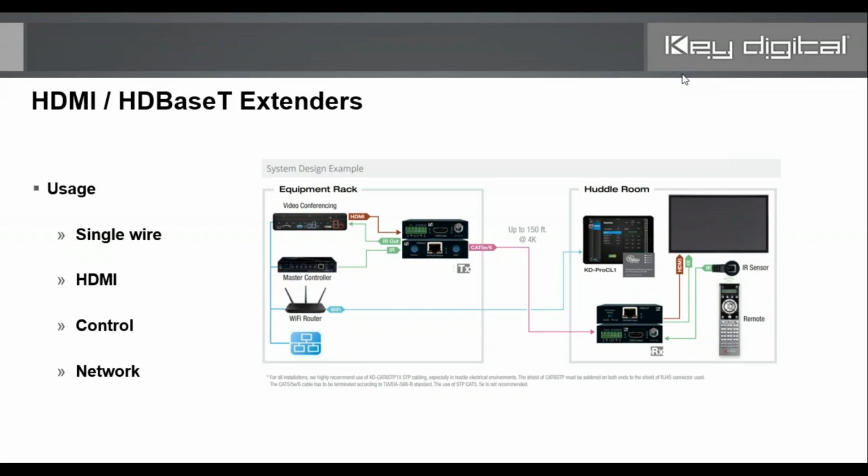But over the past decade, 2 decades, and so on, you've begun installing network wire, Cat 5, 5E, 6, 6A, 7 cabling at all of your job sites, and usually 2, 3, 4 runs of cables per run. That led to the proliferation of using HDBaseT extenders, because anytime you need to extend HDMI over a single wire, you can do so with an HDMI HDBaseT extender.